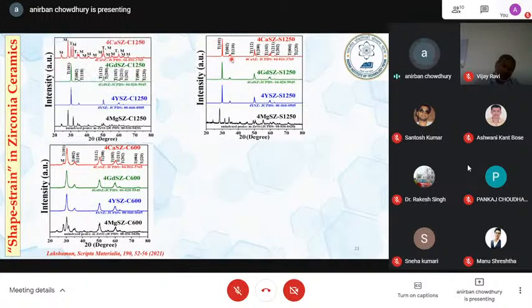Okay, fine. Then you see the same, just calcine at 1250. This is sintered at 1250. It's calcined at 1250. When you calcine at 1250, you see the biggest change. The Mg remains similar. Yttria, Y2O3 remains the same. Gadolinia remains the same. The big change is in calcia. In calcia, you see that there is a full monoclinic phase appearing, and here there was nothing.